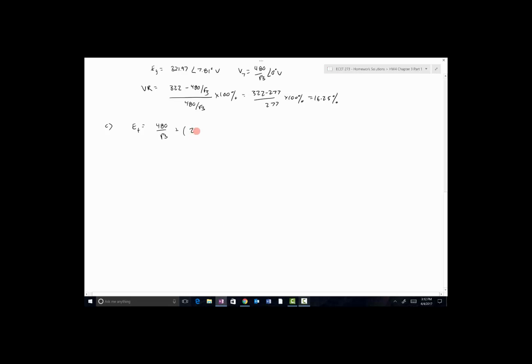240.563 amps. And this is going to be at a power factor of 0.8 lagging, so the inverse cosine of 0.8 gives you 36.87. Throw that minus sign on there to make it lagging. So that's IA.